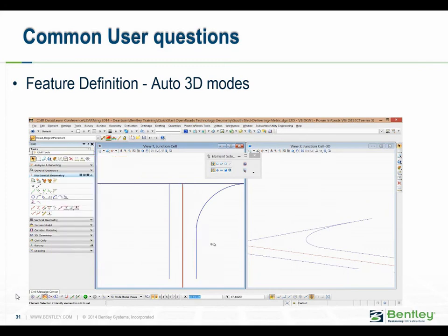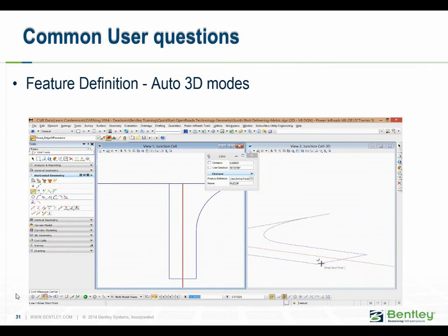The final mode that we have is a snap based mode. So if we are working off elements that have existing geometry and we are trying to snap out and close the shape, in this instance just closing out in between these two lines, we can snap and apply and close the shape out, and it adopts the Z value of the geometry that you're coming off.